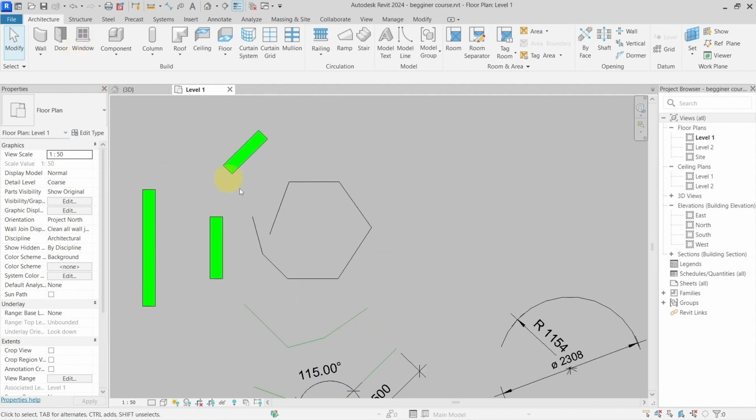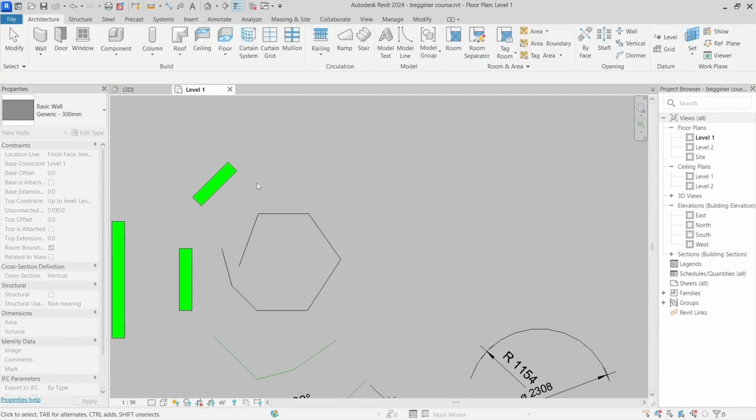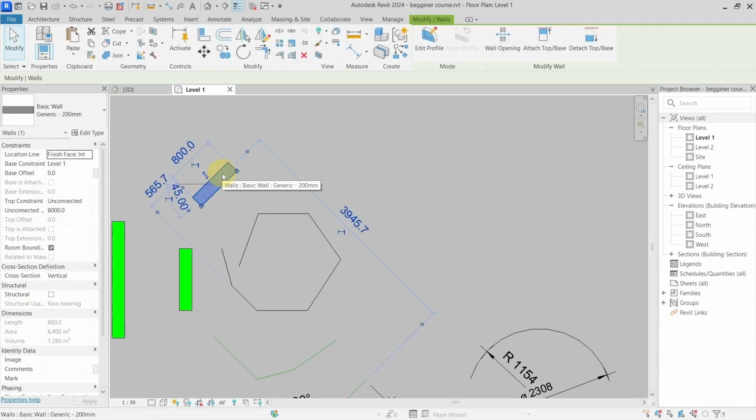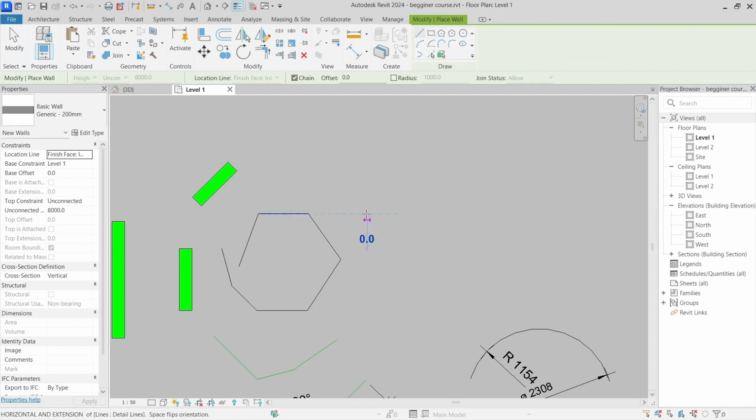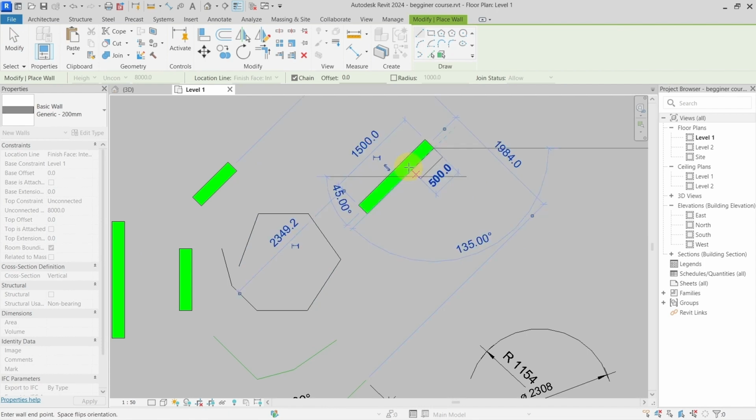So if you are doing something, let's say, as we have talked about before, I have a wall and I'm creating the wall. Okay, I will use this one. I will go with the shortcut CS to create similar. And now I can just write my number here and it will be 1500 millimeters long. And I can go like this.